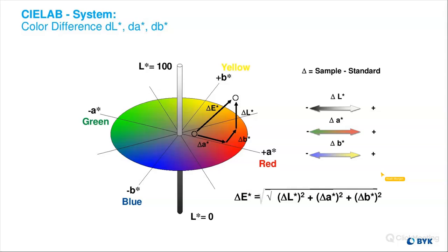But delta E is really your total color difference. If you have, let's say, a primer that's going down, and then a base coat that has a very low opacity, and you can see the primer through that, the primer is definitely going to play a role. You're looking at what the influencing factors are in your total color difference, and whatever you can see is changing that, if that makes sense.